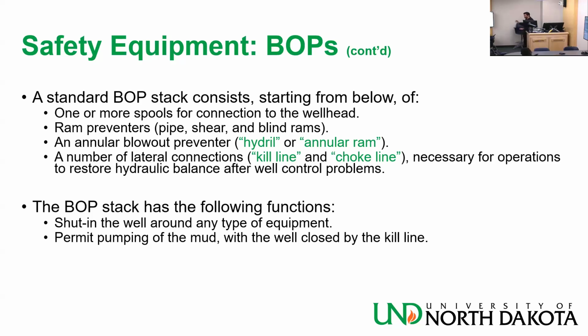The BOP stack has the following functions: shut in the well around any type of equipment, and permit pumping of the mud with the well closed through the kill line. So yes, I shut in the well, but I want to be able to circulate, not like when I'm drilling, maybe at a slower rate. I need to inject and produce fluid, let mud go in and have mud go out.